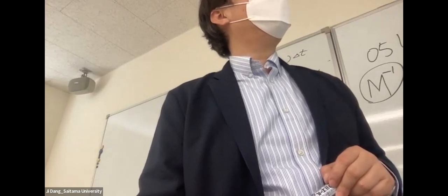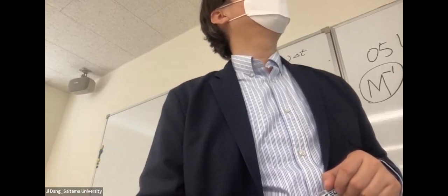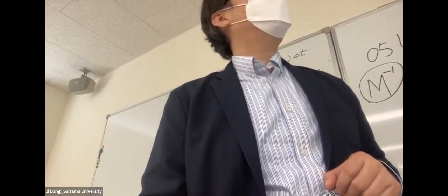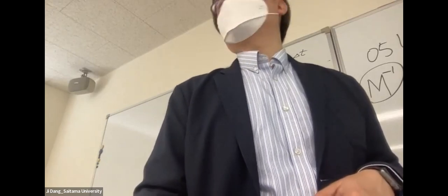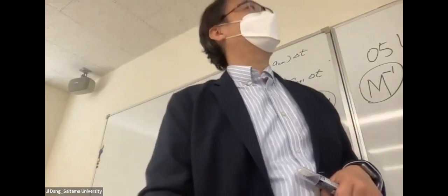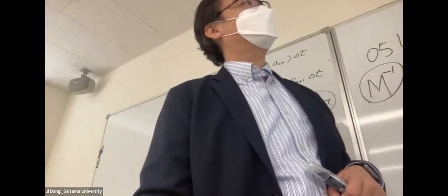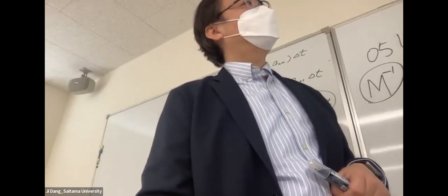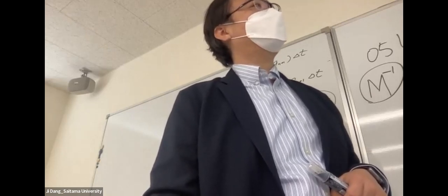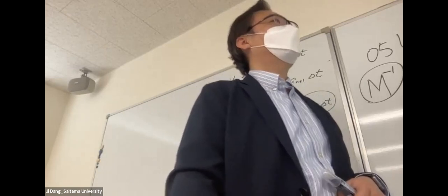So after correction, the accurate delta n plus 1 will be the old one, which we're using for prediction, and minus this term. So this term is the corrector. This is the predictor part. We predict using the linear result, but correct them with the nonlinear force. So this is a predicted delta A, then this should be the corrector. And so we say that this is a corrected response, or say response incremental corrector.